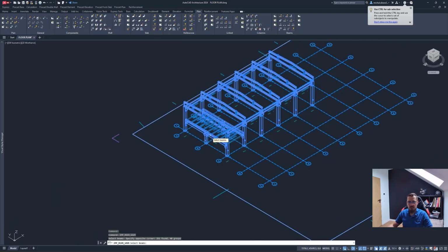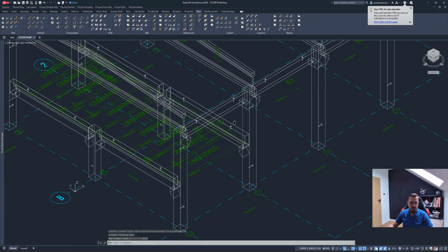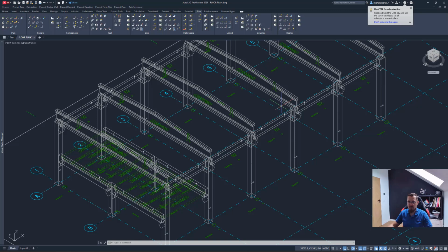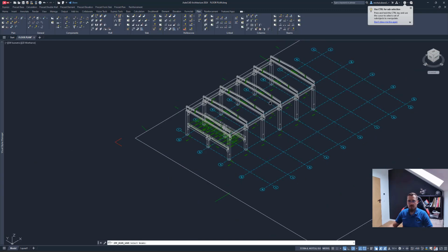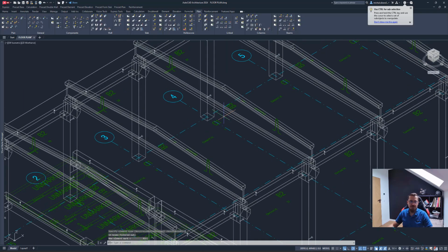I'm going to select all of them again, and now I'm asked, because there's a distinction between the non-stressed and pre-stressed beams. Let's go with non-stressed first and make those B1s as first number. So we've got B1s as the ledge beams and B2s for all the beams going along our frames. Now we need to repeat the process for the beams, because we also need to save to the database the pre-stressed beams that we have for our roof. And they're saved, so pretty quick.